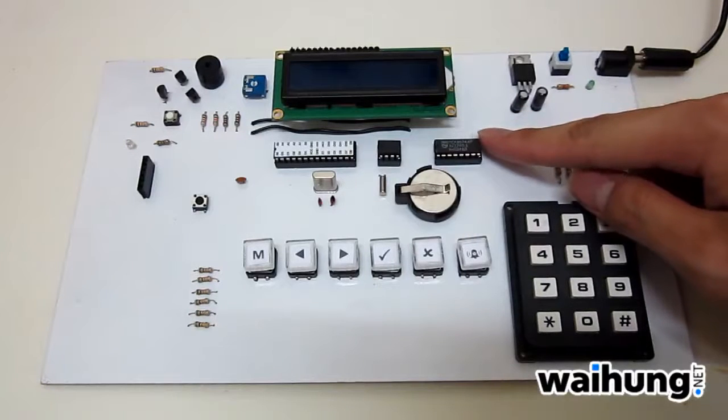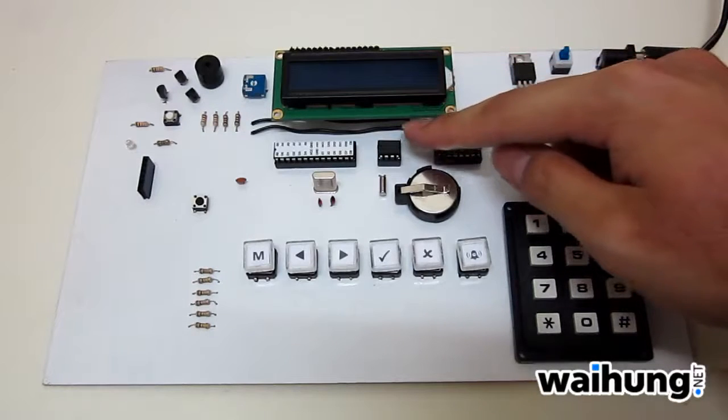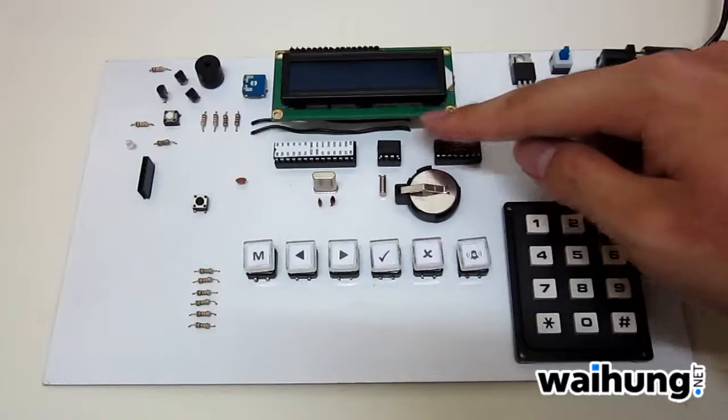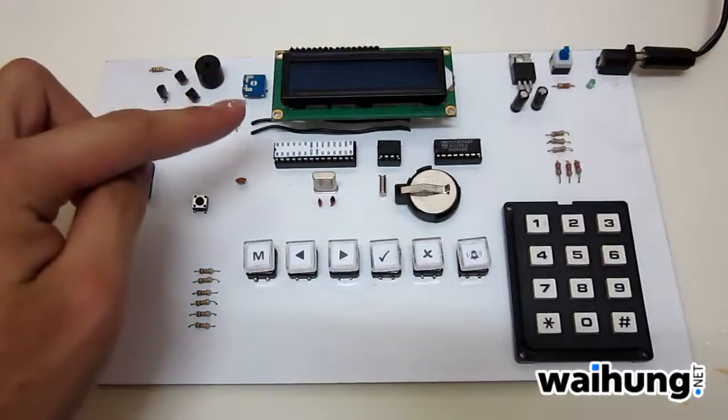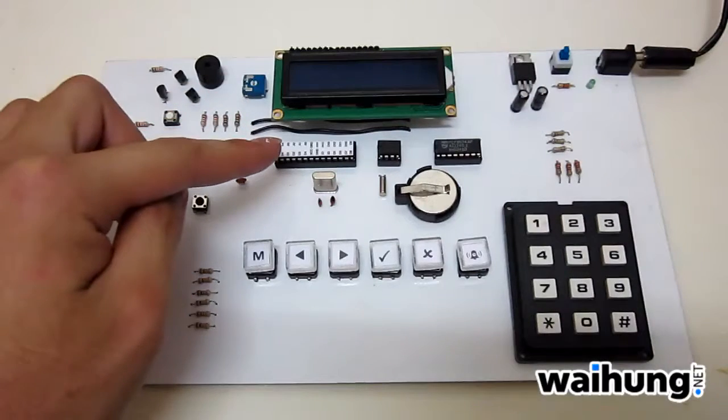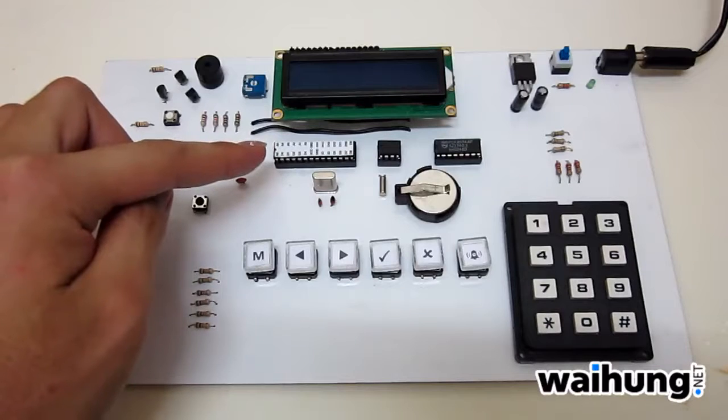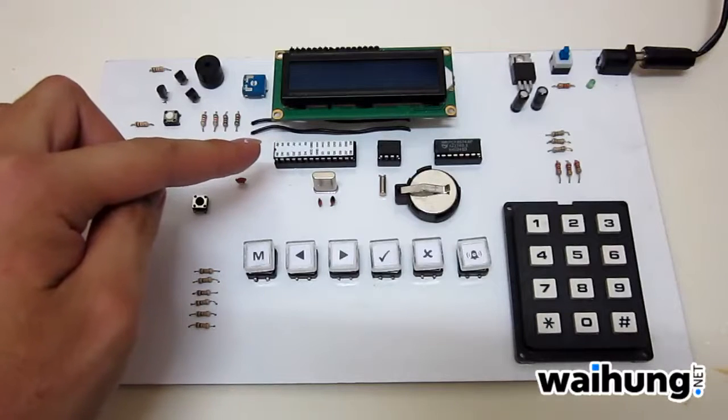PCF8574A I/O port expander running on the I2C bus. Also on the I2C bus is the DS1307 real-time clock IC, the ATmega 328P microcontroller with 32 kilobytes of program memory, runs on the Arduino code,